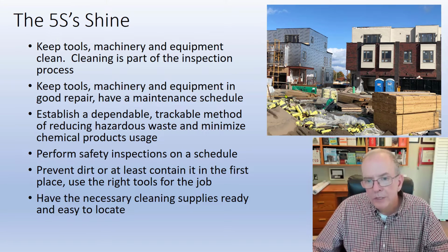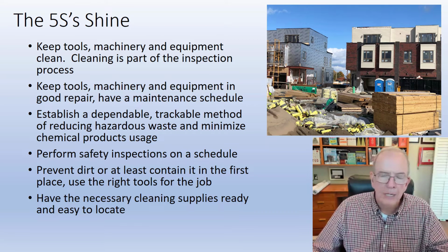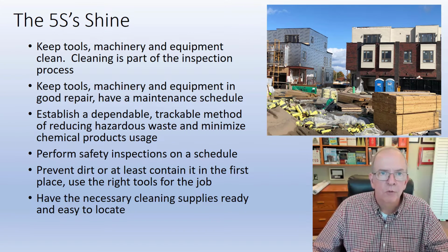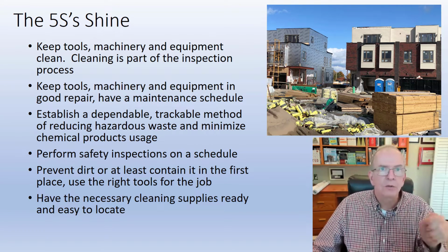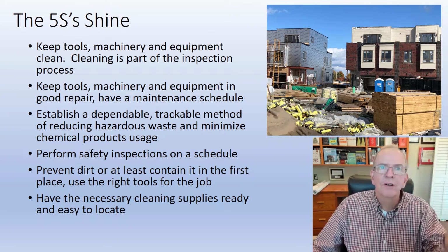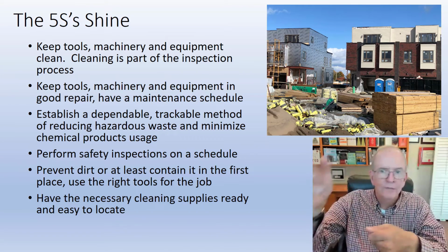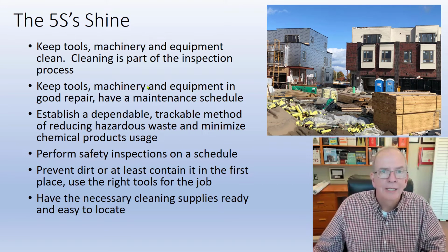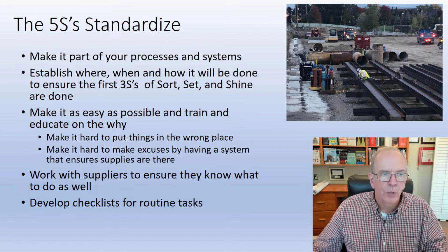And that would include, I don't see the mortar mixer here, but I think it's just off the screen, maintenance on the mortar mixer, making sure it's getting greased at the proper points in time, making sure that it's cleaned properly. Sometimes they're just caked with mortar that's dried out, and then they hit it with a hammer and then pieces of mortar fall inside. And sometimes when they're mixing it, little pieces fall into the mortar mix. The bricklayer is trying to lay the brick, and then it's rocking and they're wondering why, and then they've got to lift the brick again. That's all waste, right? So you try to organize it so that it is going to be smooth and flowing.